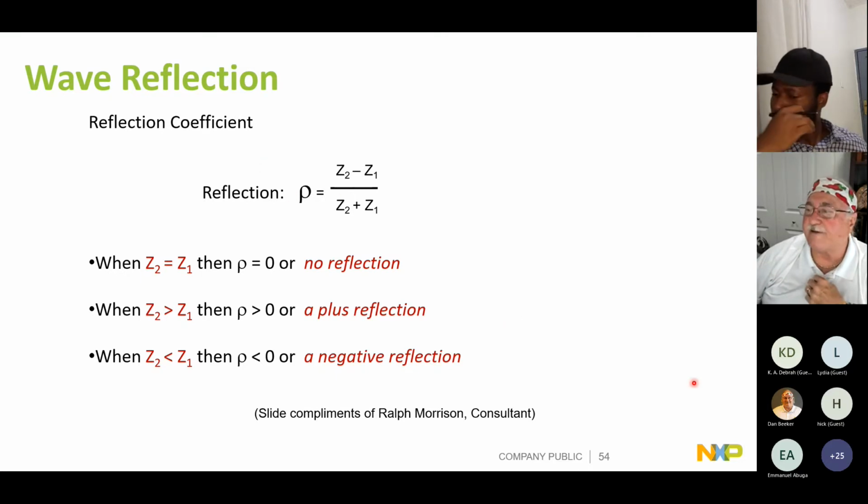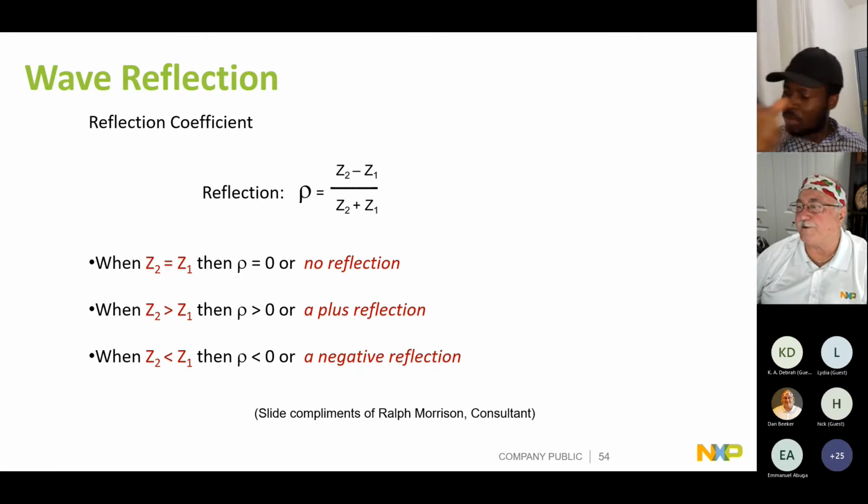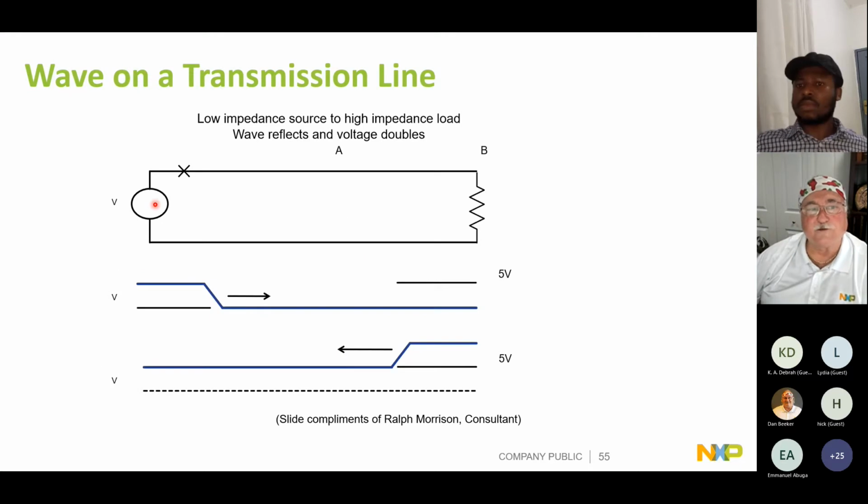it's so important to know how fast these transistors are switching. So if I've got a switch, power source, and a load, and I'm farther apart than the quarter wavelength, I will start a flow of field energy. The wavefront is moving around. It comes to the receiver. Not all the energy can go into the receiver, so this bubble goes back the other way.